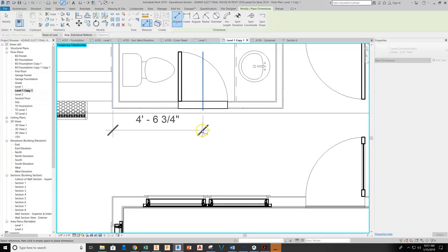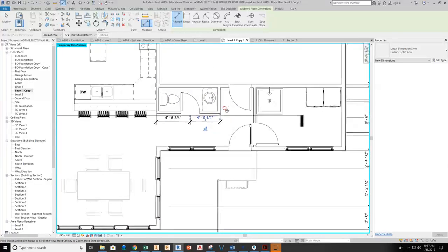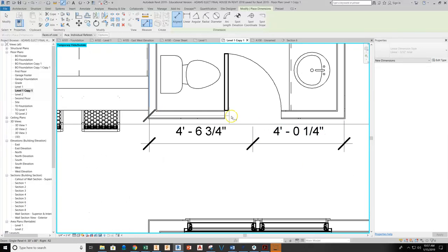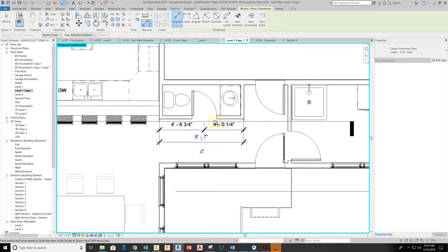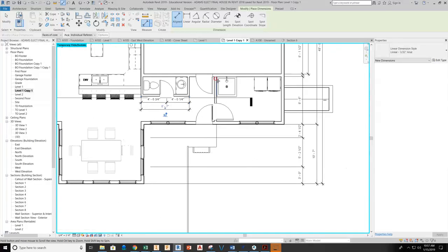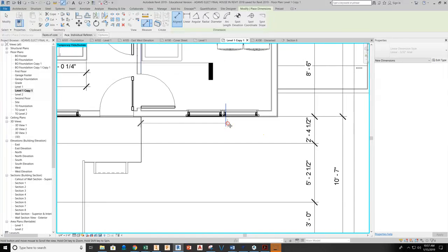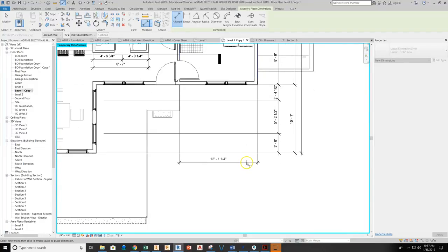So I am going to set up where the center of the door is going to be to the outside here. These dimensions get placed on the inside, and here they're getting placed in a nice clean area in this hallway, and I want to keep everything nice and neat. So I'll give the overall, and I'll also give the door position. I can then also dimension this wall. However, this wall would actually get dimensioned from sheeting face here to stud face, and that would actually get pulled out to there.